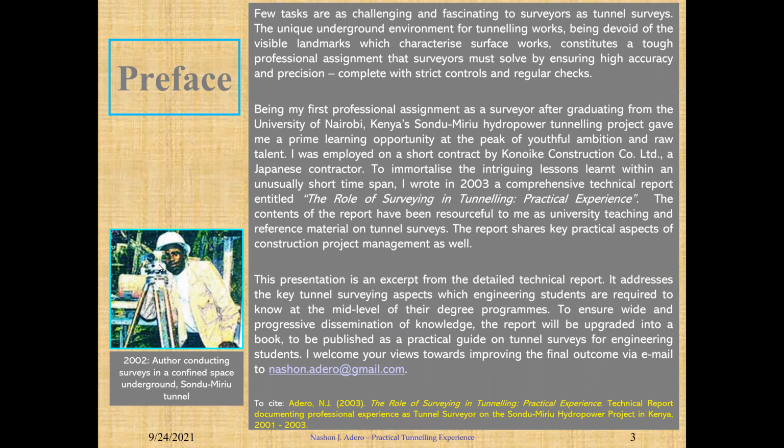A level doesn't have that big vertical circular section, or a circular section on the side, and a level doesn't have that freedom of movement along the vertical plane. This telescope won't move up and down. It is fixed in the vertical plane to give you accurate vertical measurements for vertical differences in height. So that is the uniqueness of a level.